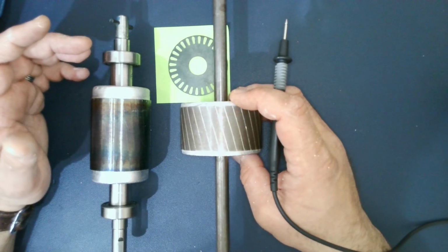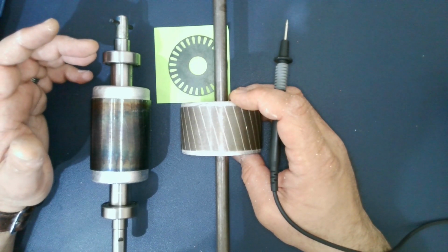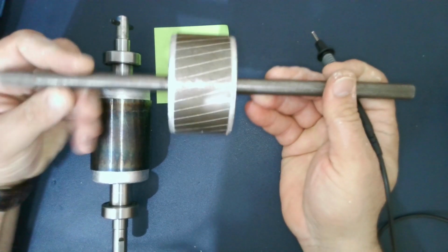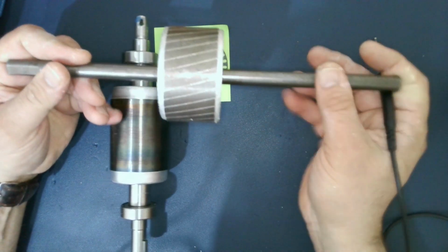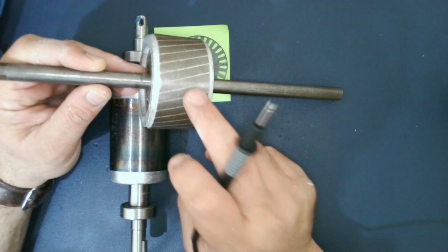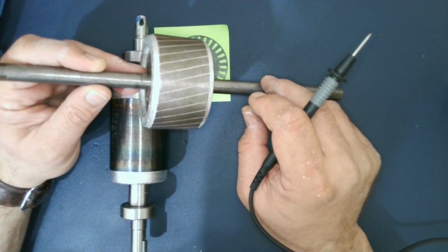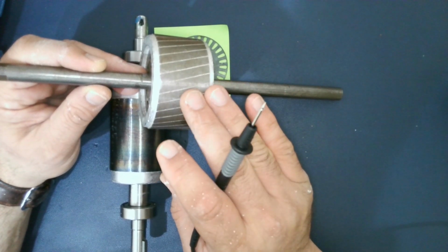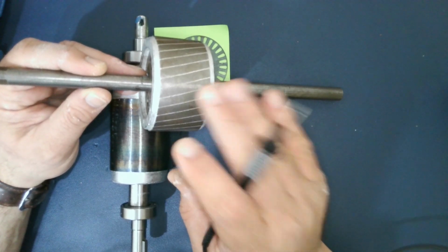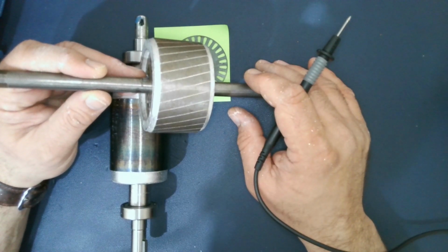Actually, the privilege or the advantage of this machine is that it is adaptive. So the rotor of the squirrel cage motor is adaptive to the stator. If you have a single phase stator, this machine is going to operate as single phase. If you have a 3-phase machine of the same size, that one is going to operate 3-phase. If this machine is 5-phase, this rotor is going to be 5-phase.